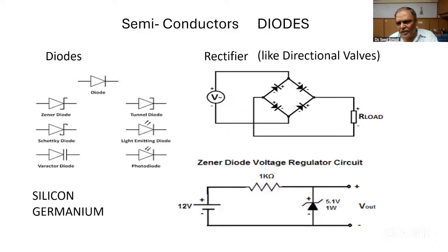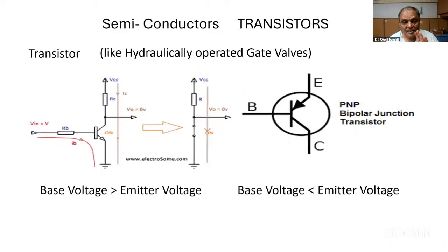So there are different types, like the diodes. Diodes are the basic ones. I learned it 60 years ago in my radio. In the radios we had at home in those days, we used diodes. Diodes are the first invention. You must remember the diode because they're used in many places in the farm also. For example, when you connect a solenoid, you must check: is there a diode or not? You must ask the guy. Otherwise, the solenoid will blow, your electronics will blow. A simple thing, many electrical engineers also forget to put it. So you must remember the diode is a semiconductor, and we need it, that's all.